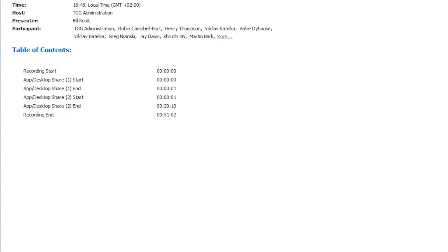Yeah. So there's some further question on it. There are specific cases for everything, but in general, the one thing that we will have in liquid cooling, depending on the manufacturer, is some kind of cooling distribution unit for sure. So that's going to take up space that wouldn't be there normally for the air cooled, but if you have an air cooled data center with CRAH units in the data center, it's still going to be less space. So it depends. I believe the more common case will be to use less space for water cooled, but maybe there are some that do. So it's a good question. I can't answer it based on the information we have.